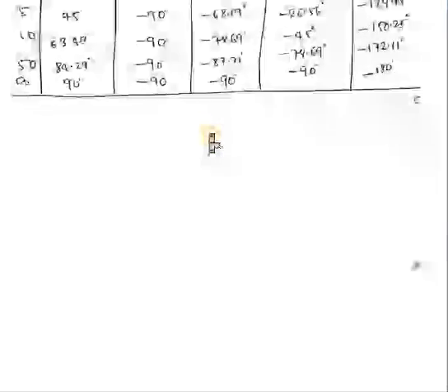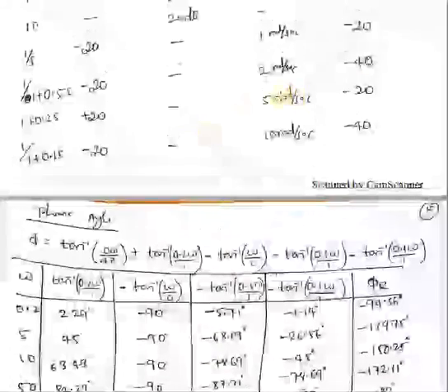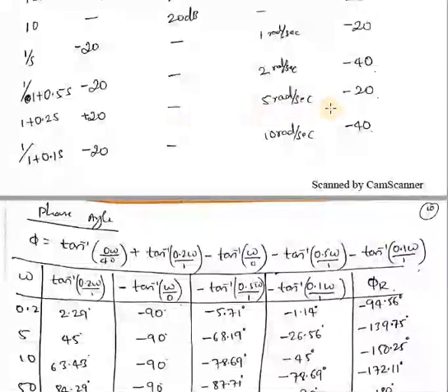Sorry, it is not minus 60, it is minus 20, because in this table, it is a cumulative table, and for this 0, minus 20 is the slope. So that means from 5 to 10, it will be a minus 20 dB line, parallel to this 20 dB line. After that, it will be minus 40 till infinity. Okay. So this is the